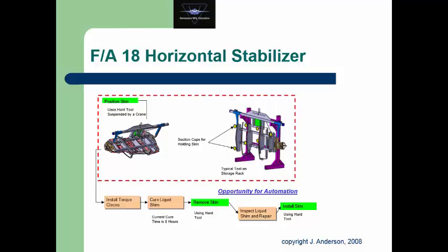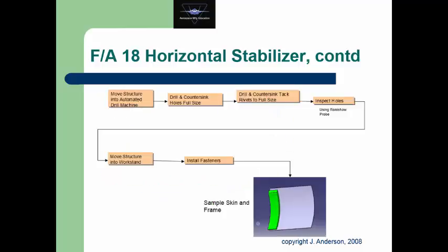Or you put a spacer in between the surfaces of the framework and the skin. Well, you can't make a shim with perfect tolerances that absolutely fits in a gap that's due to the error in manufacturing, small errors in manufacturing of the skin and the frame. So you use a liquid, a resin, that goes in there and then solidifies.